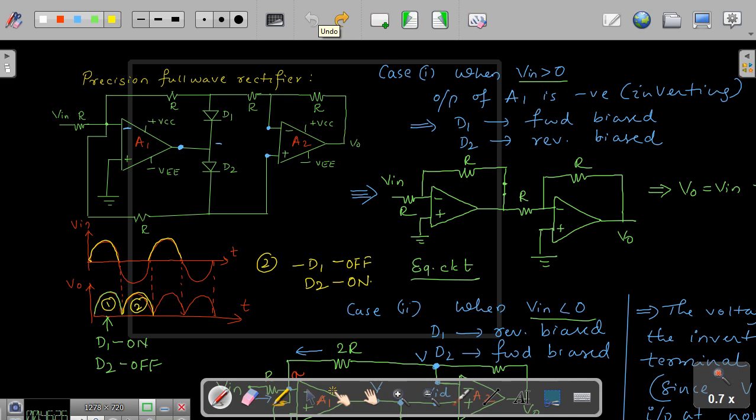And you can try the same problem which I have given for the previous case, that is the half wave precision rectifier. Design a non-saturating precision full wave rectifier, non-saturating in the sense it will not go and saturate at a particular value. Maybe to produce a 2 volt peak from a sine wave of input peak value of 0.5 volts. The same frequency you can take 1 megahertz, and you can use the same bipolar op amp with plus or minus 15 volts.